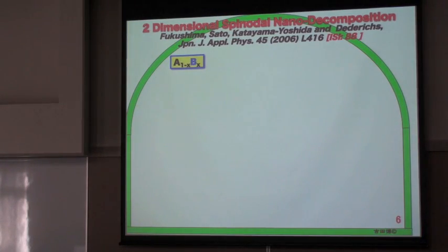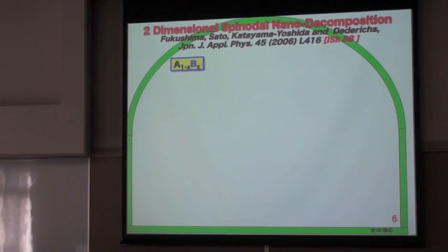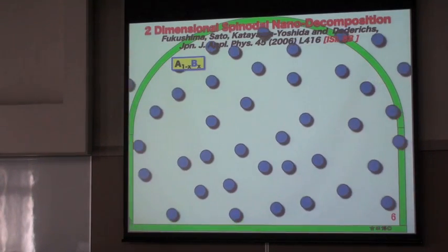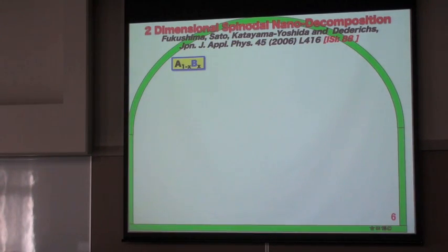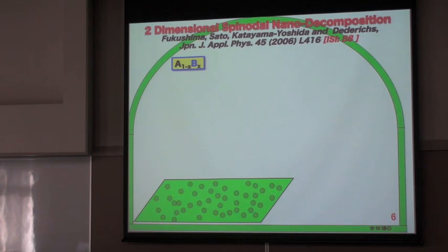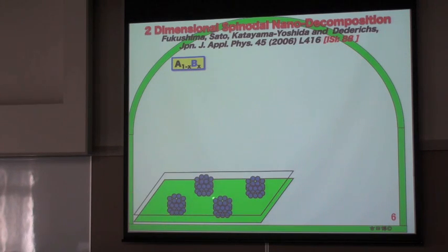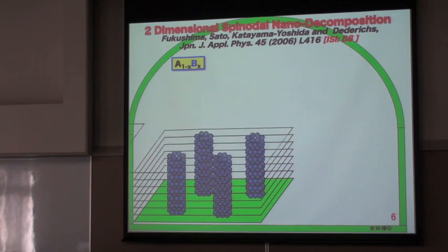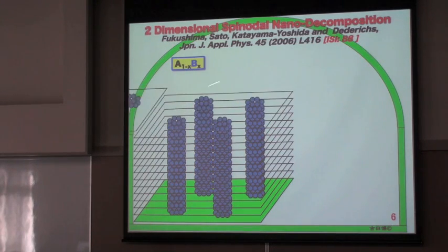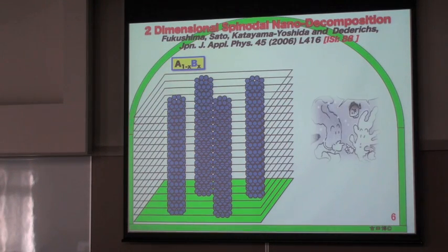Of course, you can control the dimensionality of the crystal growth. You have a substrate here. Then you put on the A and B atoms, for example, zinc and chromium in zinc telluride. Then homogeneous doping, and after that you can start diffusion here. Then you can see very small clustering like this. Then you can quench the crystal growth and grow the next layer. During the diffusion, this atom stays just on the top because this is just oil and water. Then if you grow the crystal layer by layer, you can grow the B high concentration region inside the A matrix.